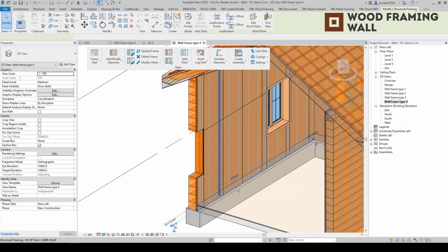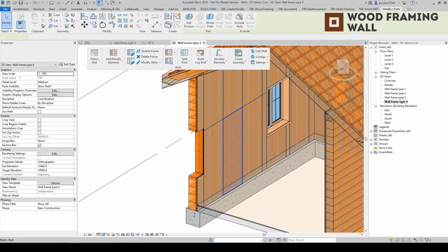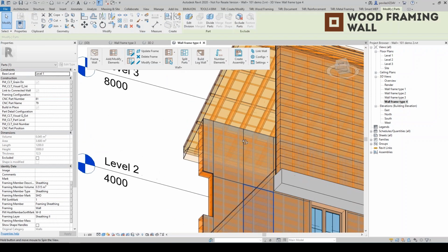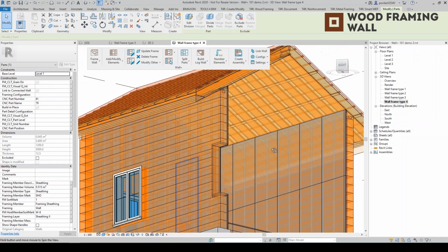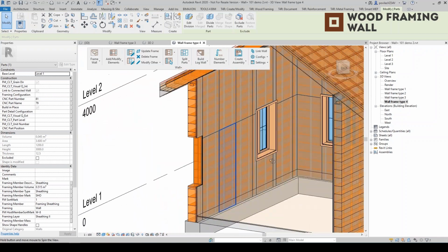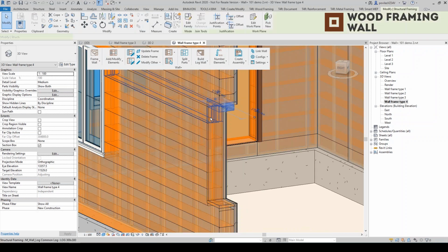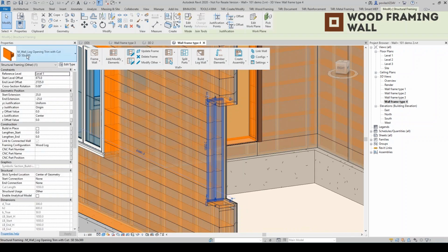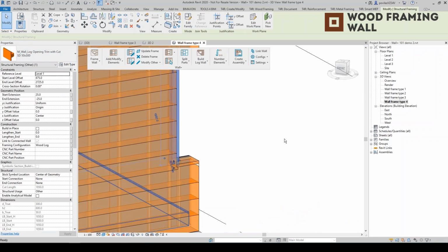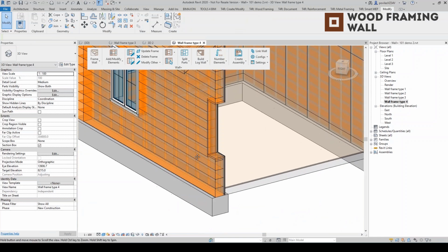Okay, so my plasterboard is here. Entire sheets, they are placed according to the predefined rules. Okay, and the logs were sort of cut according to the window opening, and additional detail is placed. Okay, opening, trim, wood cut. Okay, so all that is generated automatically.